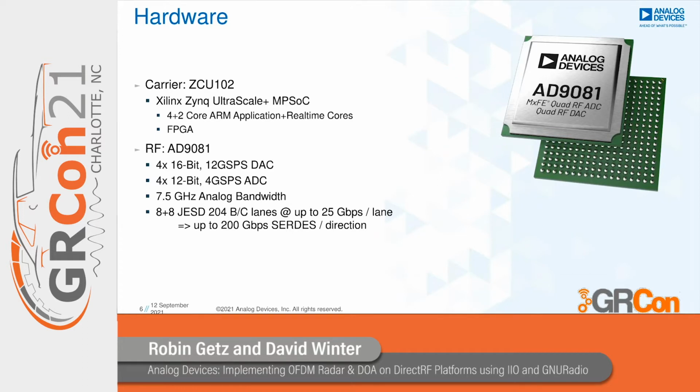Now, DirectRF means we are sampling at RF frequencies, so we have a 12 gigasample per second DAC. Actually, we have 4 12-gigasample-per-second DACs and 4 ADCs, though you don't have to sample the first Nyquist band, so the ADC bandwidth is actually 7.5 gigahertz, and you may need some anti-aliasing.